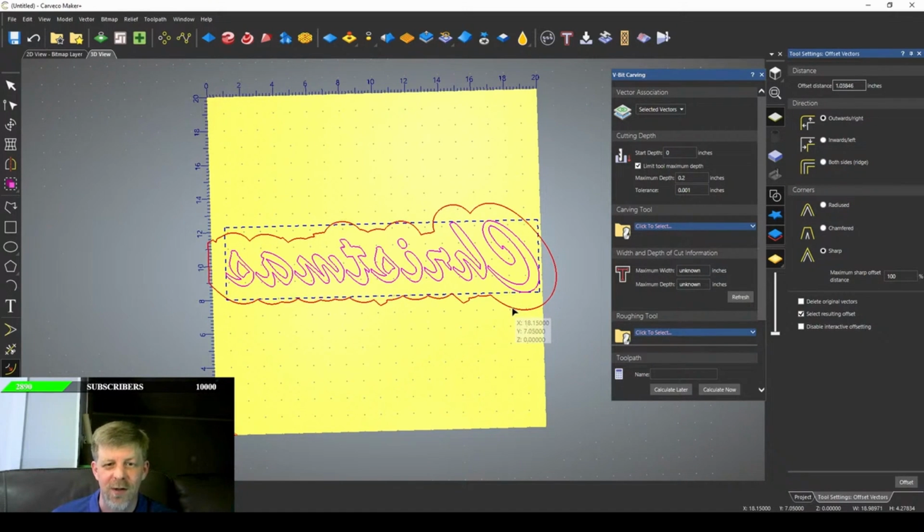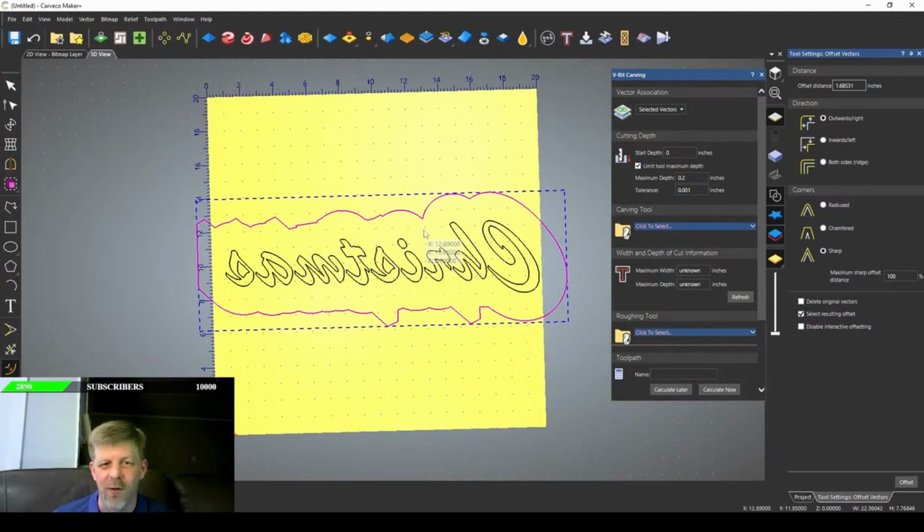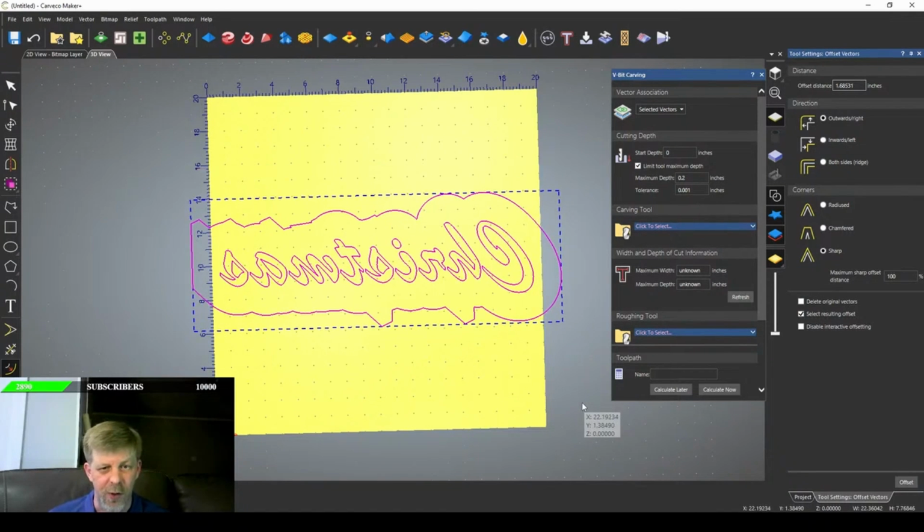Now, I'm just going to tell you that I like to make sure that it's out far enough to where I could put this on a bandsaw and just cut the letters part out. I want to give enough material around here to where I could come with another saw and cut this off, and then I have all of this part standing proud as a male part. I hope that makes sense. Another thing you can do, you can see that our C is really close to the edge over here. We can move this over so that we put most of our lettering in the center of the material. And it's okay that the bit's going to go outside of the material here. We're not really worried about that.